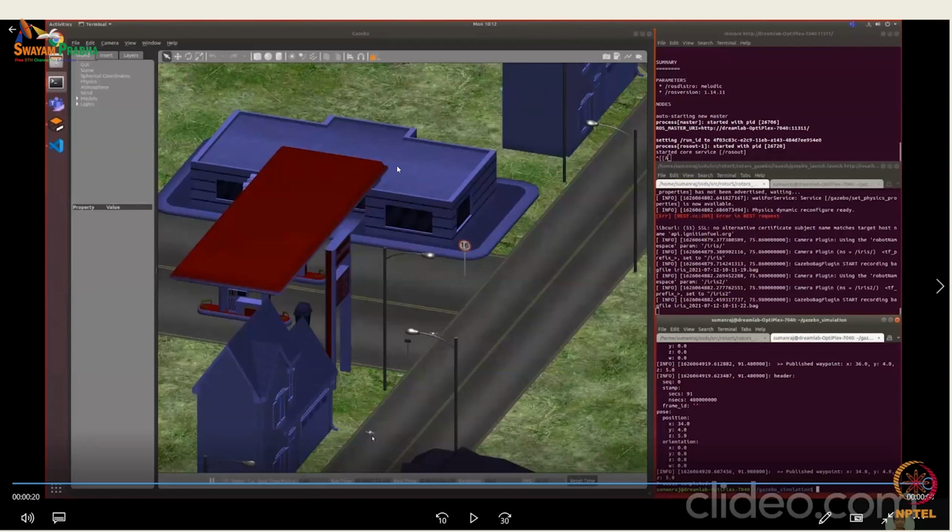How do we integrate NS2 or NS3 with Gazebo, if we want to test the communication in real time as well? Right now we saw one demo of NS3 with SUMO and one of ROS with Gazebo. For your application, we'll have to have ROS plus Gazebo plus NS3. That will be the actual architecture for your problem statement, I guess.